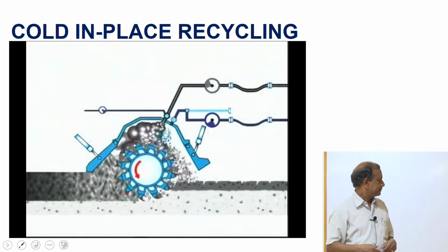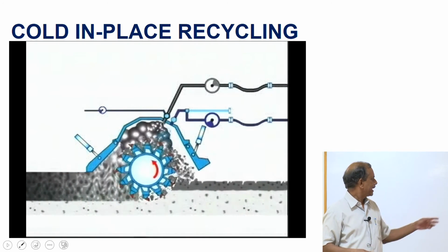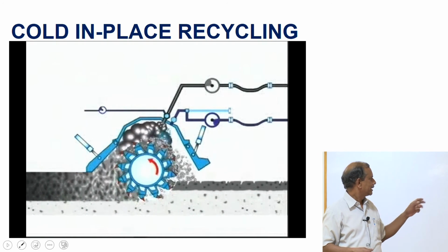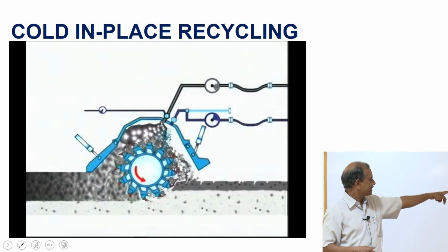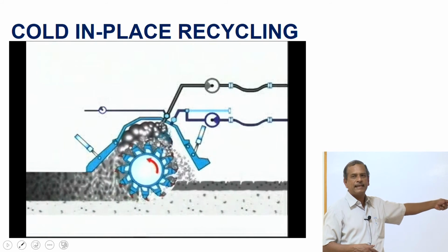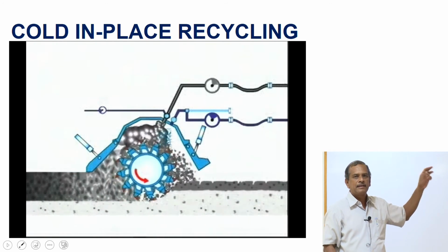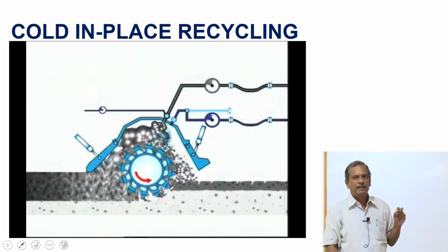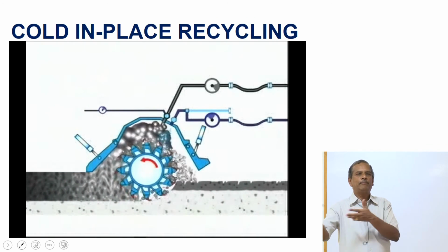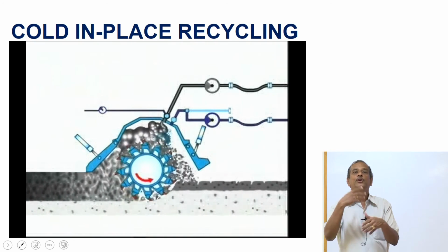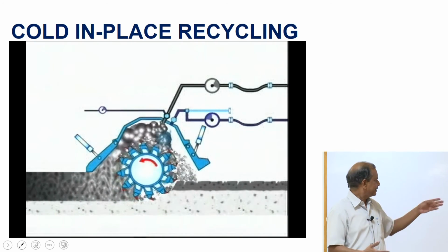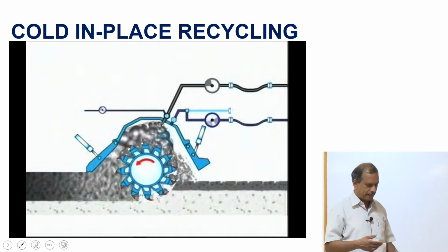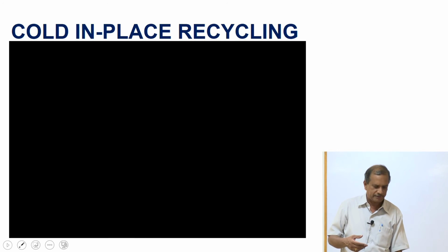I can mill the material. I inject the foam bitumen. So, this layer is called a bitumen stabilized material, or a BSM. So, I am not throwing out the whole deteriorated pavement material, I am trying to reuse it again. Because the material has deteriorated, I am trying to strengthen the material properties by using foam bitumen. I can reduce the thickness of the layers.